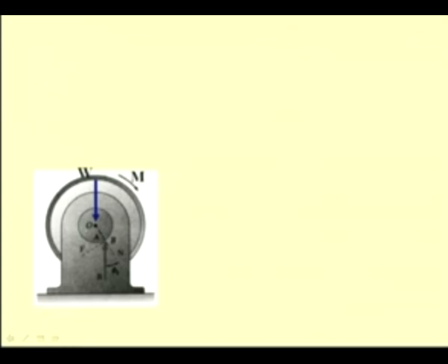So, that is what is represented in this picture. For a constant motion of this axle, the point of contact has shifted from, say, the lowest point A to the point B, and this is the kinetic frictional force existing between the axle and the journal. This is the normal reaction along the radial line, and the resultant of these two is R, which is vertical and equal in magnitude to W.